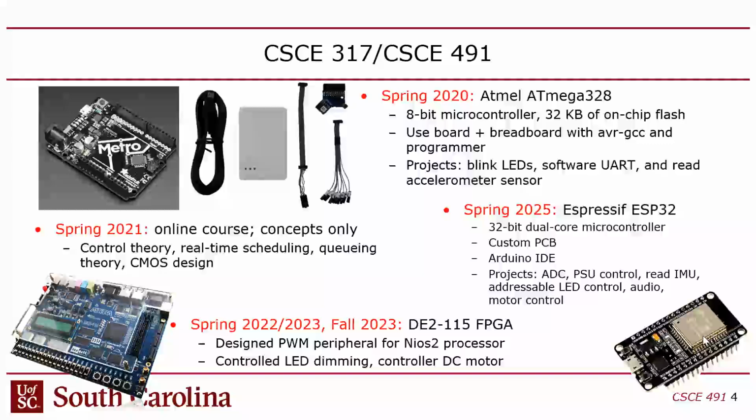So our idea was to move away from the FPGA and switch to this ESP32, which is a lot more powerful than this guy. So this is a 32-bit processor, multi-core. Instead of 16 megahertz like that thing ran at, it's 240 megahertz. So it's probably 10 times as powerful as that one, if not more. Also, it has Wi-Fi and Bluetooth built in. That's what the ESP32 was originally positioned for, the wireless capabilities.